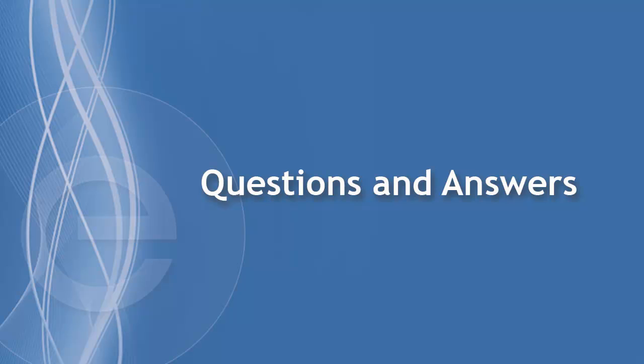Somebody pointed out that I have the wrong version here. There is a newer version of C37.102 that includes a hybrid grounding method they're recommending, which is a combination of low resistance grounding and high resistance grounding. I was trying to avoid getting into that. It's somewhat complicated to explain, but it basically combines the elements of high resistance grounding and low resistance grounding. For new systems, that's something you might want to take a look at. This says 1987, but I believe there's a later version now available. If you buy it, I'm sure you'll get the latest one.